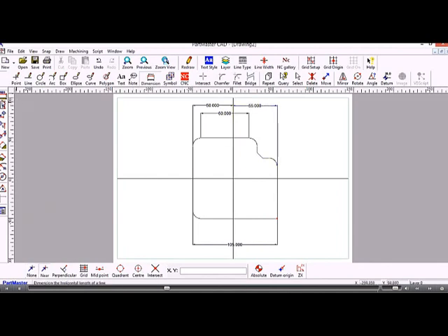The same thing works with the vertical style of dimensioning. If we indicate just the line, then it indicates the length of the line. If we want to dimension between 2 points, we can simply hold down the Shift key. The snap mode is set to near, so it's locking on to the endpoints of these lines and arcs, and so on.